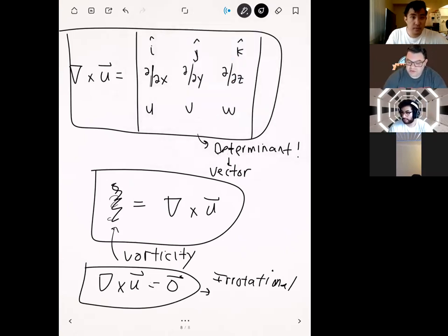Yeah, so your tornado is the vorticity? Yes. The actual Greek symbol for that is called zeta, but I'm really bad at drawing zeta, so I just call it tornado. It's a little easier for me to remember like that, because tornadoes like to swirl around, so that's the same expression for vorticity. Vorticity is not exactly rotation, but it's a way that you can quantify rotation.